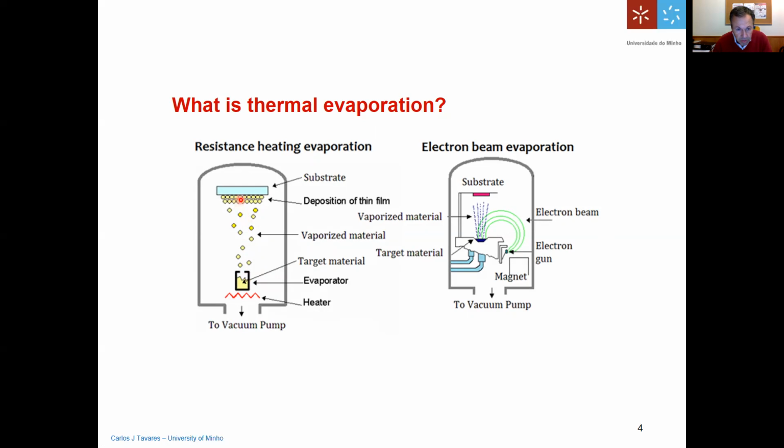film on your substrate. So you really need to have vacuum inside this process. You need a vacuum system. Otherwise, these evaporated atoms or molecules will collide with the molecules of the gas from the residual atmosphere, and therefore the energy of these particles, these yellow particles, will be reduced from these collisions.